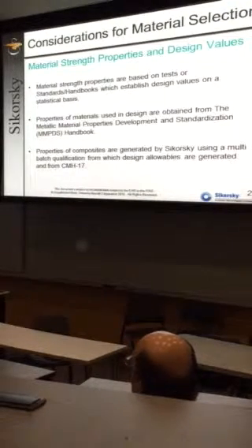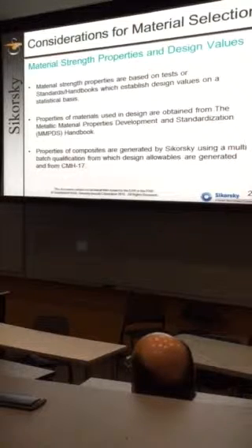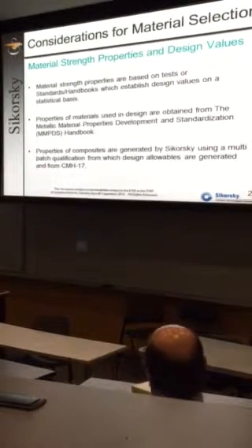Mechanical properties, we typically do testing. I'll show you a chart coming up of how we do that philosophically. But there's also guidebooks. There's MMPDS, which is the handbook for metals, metal properties, static and fatigue. And then there's CMH-17, which is a composite materials handbook, which will give you properties for industry accepted composites.